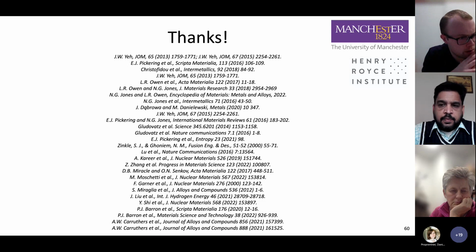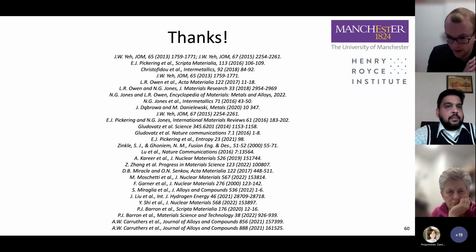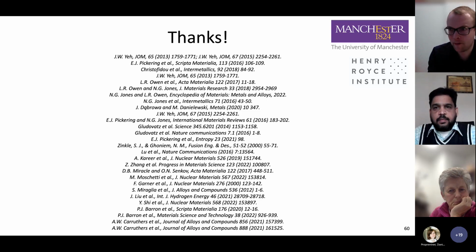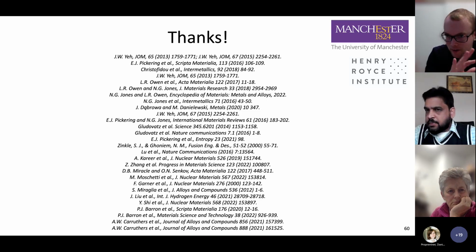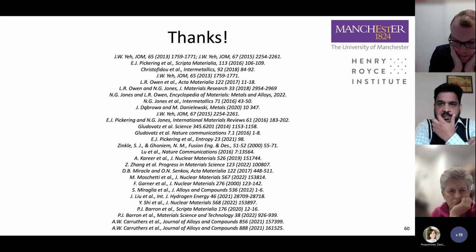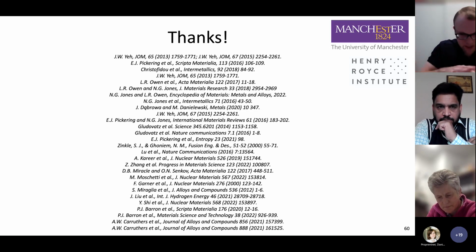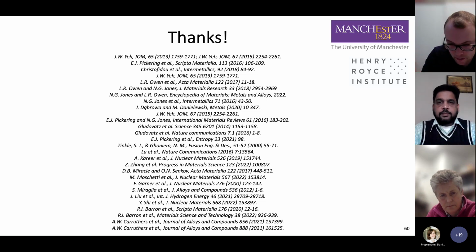I know that Dave Armstrong at Oxford has done some historic work where he's looked at the effect of nitrogen pickup, for instance, in some of these alloys, and you can form totally different phases just based on quite small amounts of nitrogen. And if you're not careful, you would think that they are not nitrides, but some other phase if you haven't measured the nitrogen. So yeah, it becomes really tricky, actually, in particular with those refractory alloys. There are some alloys that don't seem to mind so much, but when it comes to other alloys, it's a real problem.